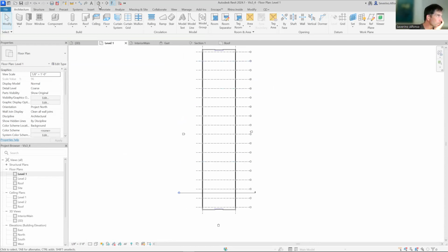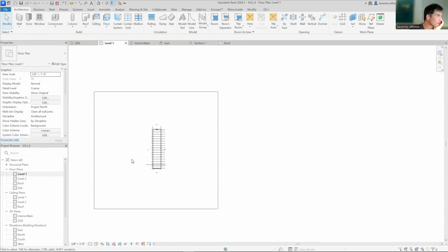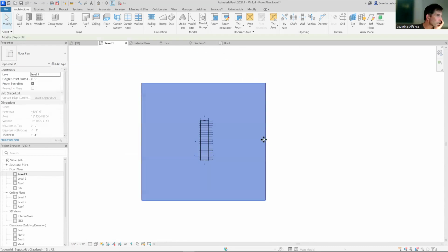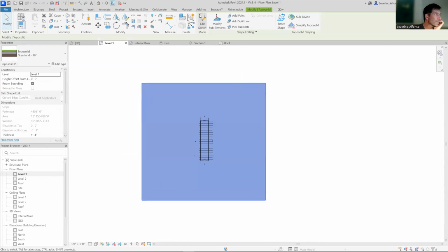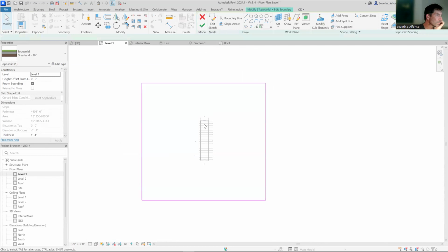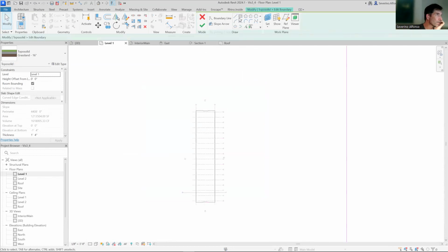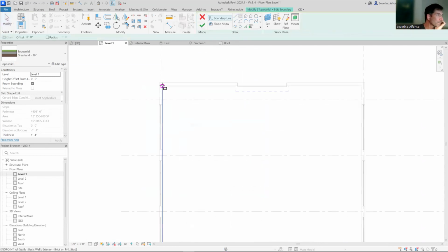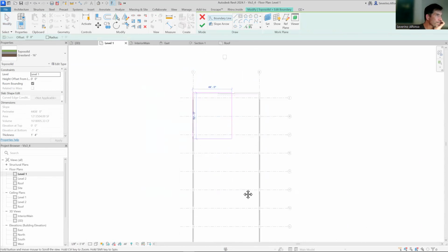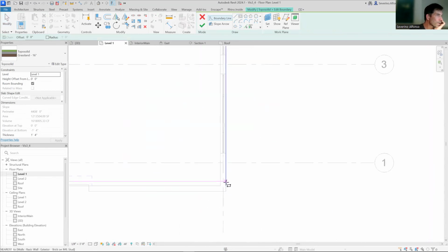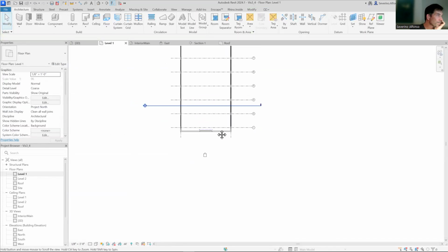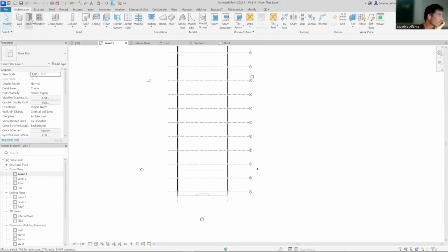But I want to do a little bit of the floor right now because again we have grass in the interior, which doesn't make any sense. We need to do two things. First, edit the profile, edit the sketch of the topo solid. There's the surface of the terrain, and create a rectangle from the exterior. That's going to create like a void or an opening in the earth. That's good. And we're also going to create a floor.